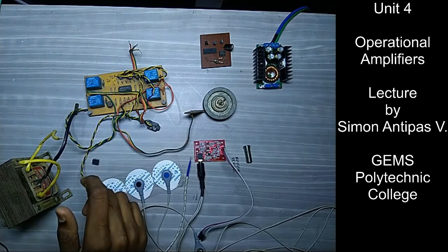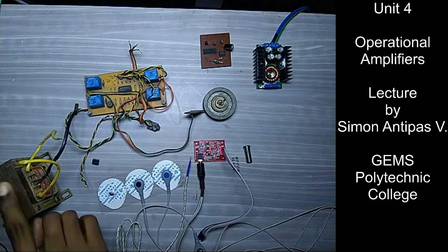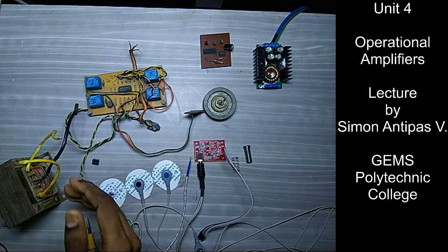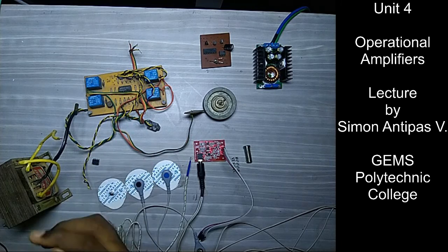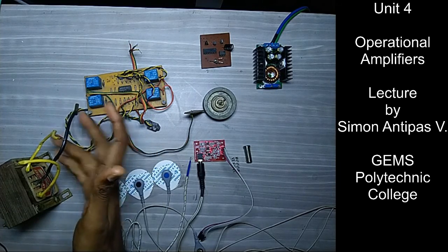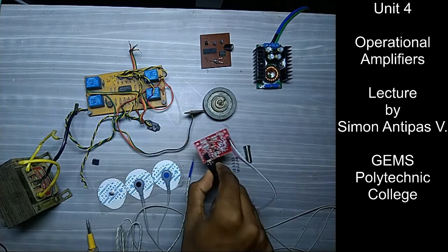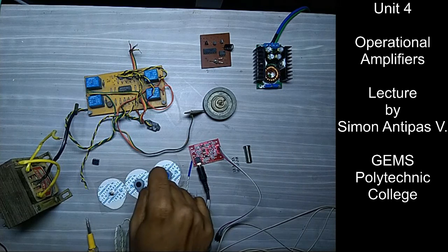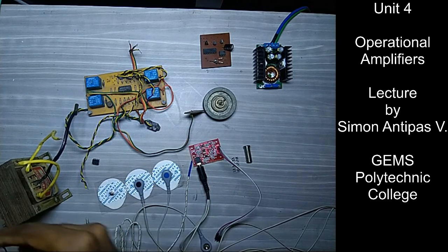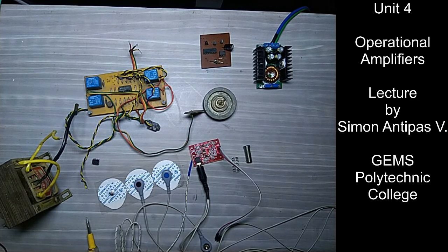Example, this operation amplifier. But these days, I could have a single power supply, and the single power supply using a voltage divider can be split into 2 power supplies and can be fed to my operation amplifier. So I don't need to give it the plus 12, minus 12, plus 15, minus 15 these days for operation amplifiers. Example, in this case, it's operating on 5 volt, and I don't have to give it dual power supplies, but it still does the job of precision amplification in this case of this AMG board.